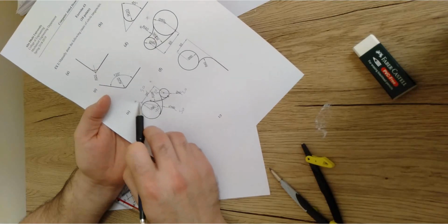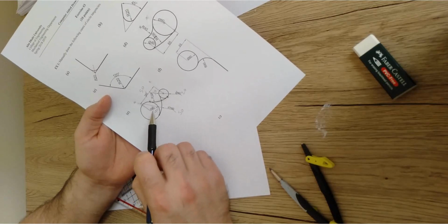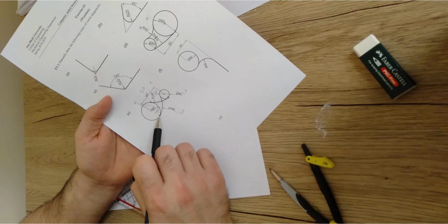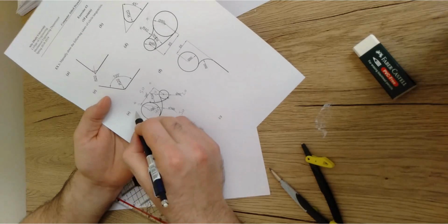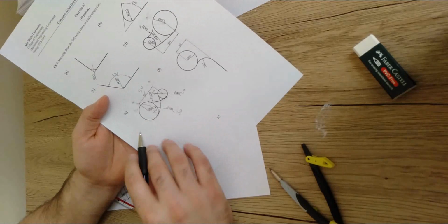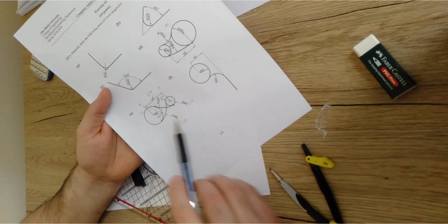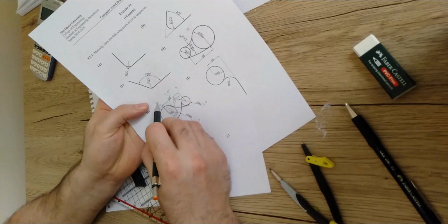It means that from the big circle we're going to subtract how much? We are going to subtract the difference between 50 and the 20, because the radius of this circle became 20. So 50 minus 20 gives 30. So I'm going to open with 30 from the center of the big circle, while from the other center, the center point should be here.